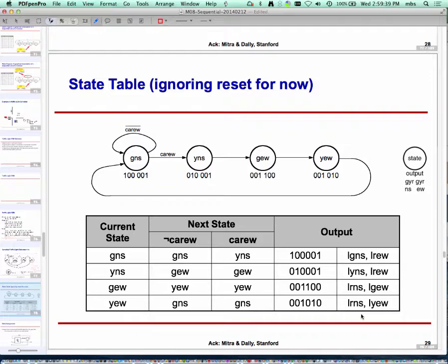I could choose a redundant representation. I could use a one-hot coding. There are all sorts of ways I can code 4 elements. We saw that very early in the course also. So at this stage there is nothing which says that any particular state should be represented by any particular bit pattern. So what I have, therefore, is this table where state names appear as just symbolic names.